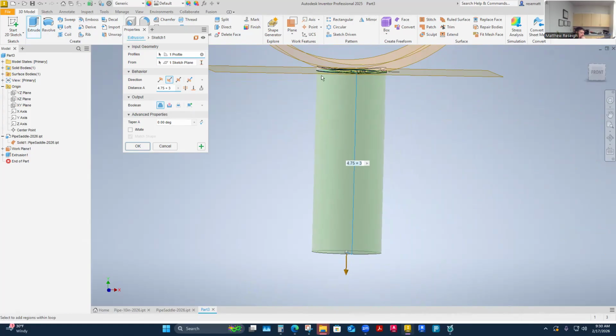There are two different solids going on here technically, but the only way you would make them two different solids, the extrusion going one way and the extrusion going the other way, is if you selected this plus. That would make those two independent solids. I don't want to do that. Default, I think, is always to join these, but there are reasons why I would need to make a new solid. And that's the other way that I'll show you, given time, even if I don't show you till Thursday, how I would do this again.